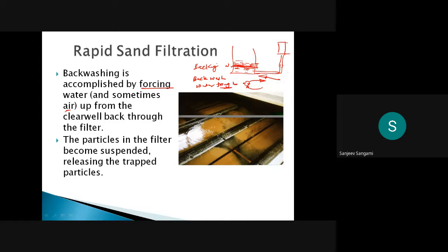The particles in the filter become suspended, releasing the trash in the particles. Normally it will be lifted up and collected. You can see the particles here. This is a channel, you can see the section channel here. From the bottom the water is lifted up and it is overflowing onto this and will be collected here. Whatever particles are entrapped in that sand bed will be removed at that point, or collected in this channel.